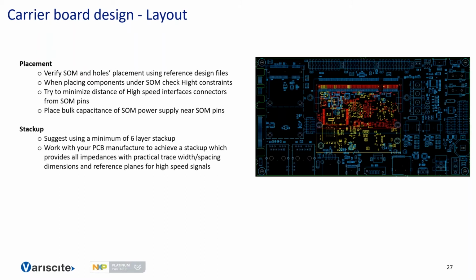In terms of stack up, for a typical design that uses most of the interfaces, I suggest using a 6-layer stack up. You can work with your PCB manufacturer to provide a stack up that will give you all the impedances with the practical trace width spacing ratio, and ensure reference planes for all the high-speed signals.